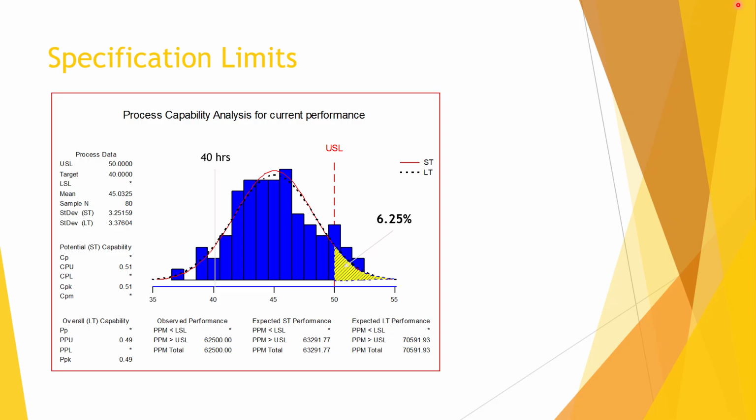For example, the two graphs below display processes with identical CPK values. However, one violates both specification limits and the other only violates the lower specification limit. To avoid mistakes, consider all of the capability indices along with a graphical summary to draw meaningful conclusions.